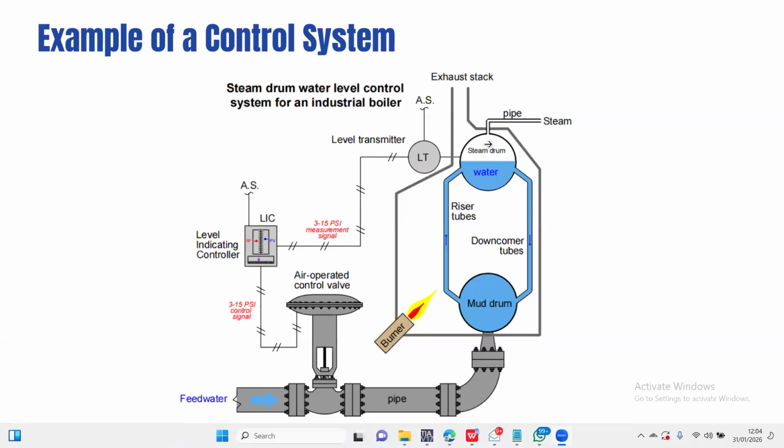But one thing I would say is that, at least with Siemens, and even with Rockwell as well, there are fault handling blocks like hardware interrupt blocks and a bunch of other things that can ensure that if a fault occurs, it remains isolated. Do you understand? It remains isolated, so that it does not take down your entire system. You see that your system is faulting, but your system will still continue running. You know that there's a fault, but it will not take down your entire system.